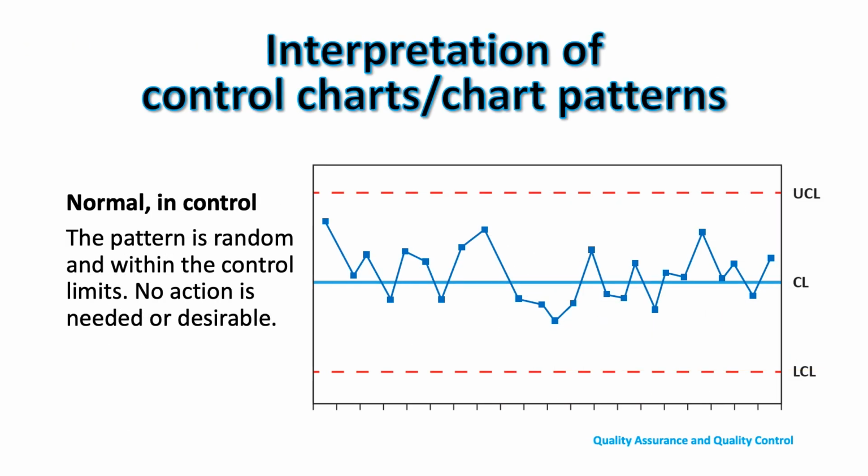Once the control charts are built, the next step is to look at the charts and determine whether there are some potential problems within the processing line. We do expect that variance will happen. As shown in this figure, all values are between UCL and LCL, even though they go up and down. This figure indicates that the process is under control and is normal.